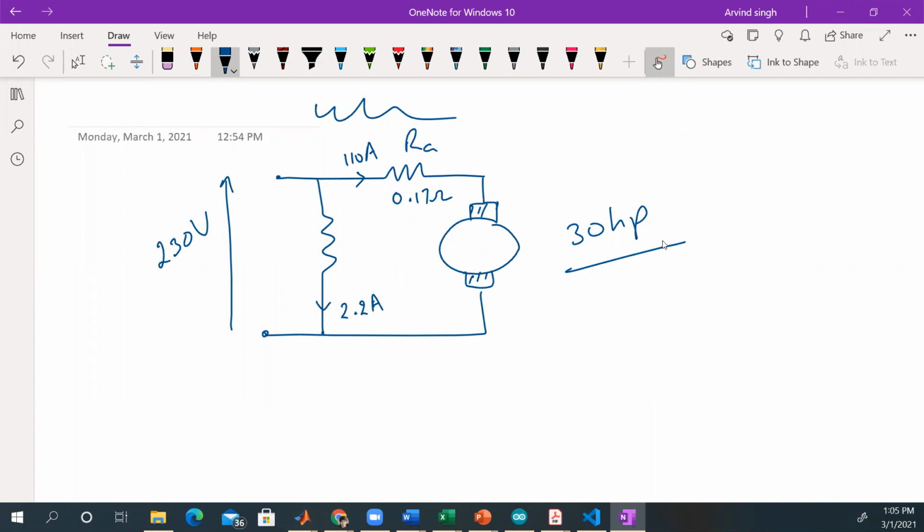You'll have to calculate typically what is the torque and power of the load that you require for the application, and then you have to select a motor. So you want to see right at the start that the motor can handle the load.